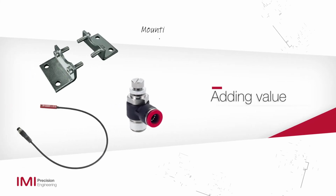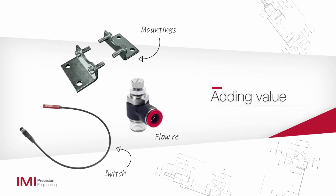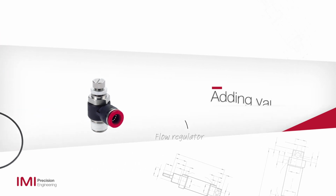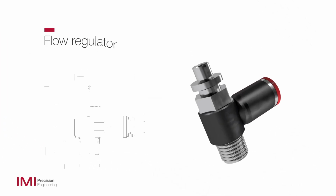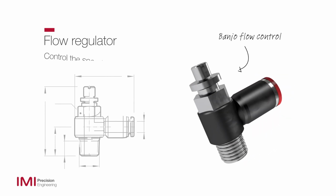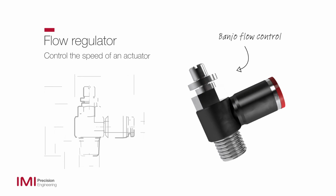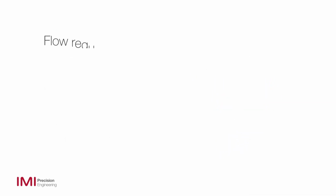Adding value. As well as mountings and switches, there are a number of other accessories available for IMI Norgren actuators, including flow regulators. A flow regulator at the point of use is the best way to control the speed of the actuator. It's always worth considering what accessories will ensure the customer gets the most from their actuator. It's a great way to add value.